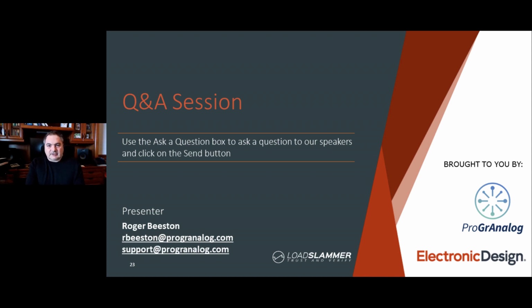There are some guidelines that Xilinx offers on their devices, and there are two guidelines. There's a slew rate, and then you could turn that into a rise time as well, if you've figured out what your worst case event peak current is through the PDN. There's also a frequency domain analysis that you can get that information from Xilinx as well.